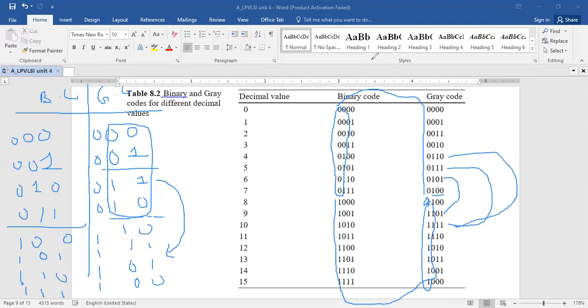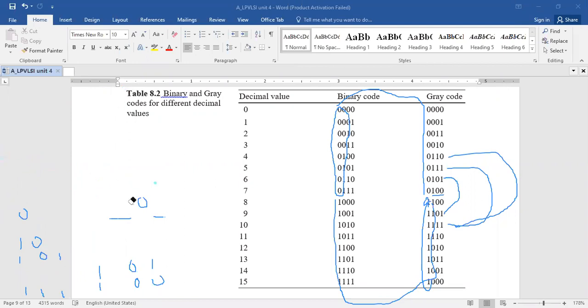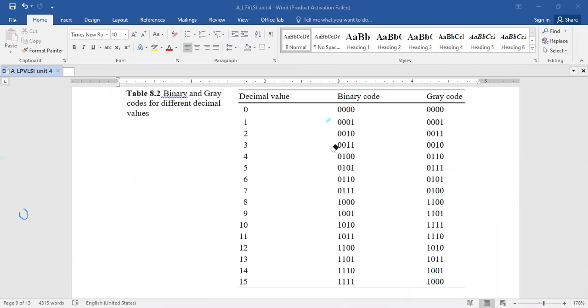Now, whenever you're transmitting the data, we'll be using a gray code representation in encoding. Then what happens here is, how can you reduce the switching activity? It has been discussed now, because if you reduce the switching activity, you can reduce the power dissipation.